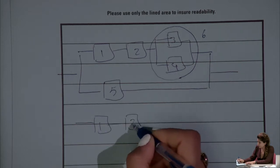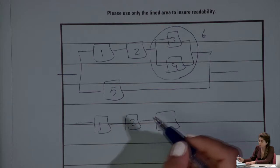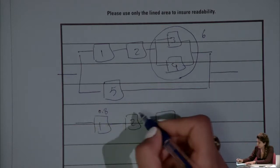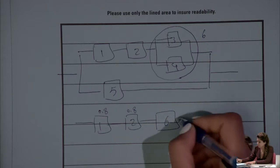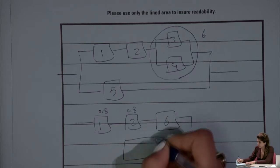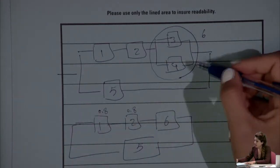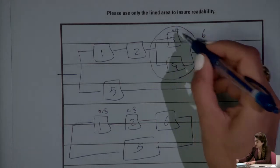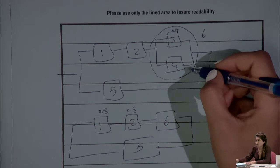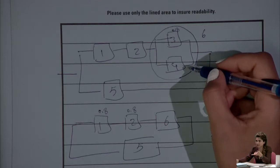1, 2, and each component's reliability is given to be 0.8. So this reliability is 0.8, this reliability is 0.8. What is the reliability for block 6? If the reliability is 0.8 and you want to calculate the reliability of this component, the reliability is 1 minus both of them failing at the same time, basically, right?